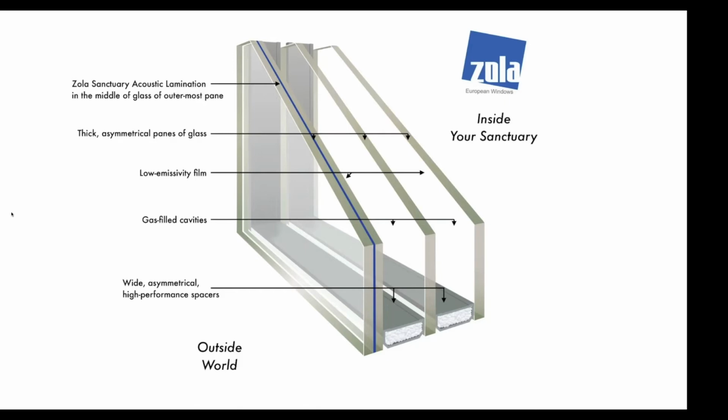Because of that, a lot of people think that triple glazed glass is always better than dual glazed glass when it comes to acoustic, and it actually is the opposite. We can make higher acoustic grade glass in dual because we have more space to put in these very thick pieces of glass that can shut down more and more sound. We only have so much space we can take up with a triple piece of glass because it's already so big that at a certain point we just can't put in thicker glass. We can't go to the most acoustically dampening glass available.